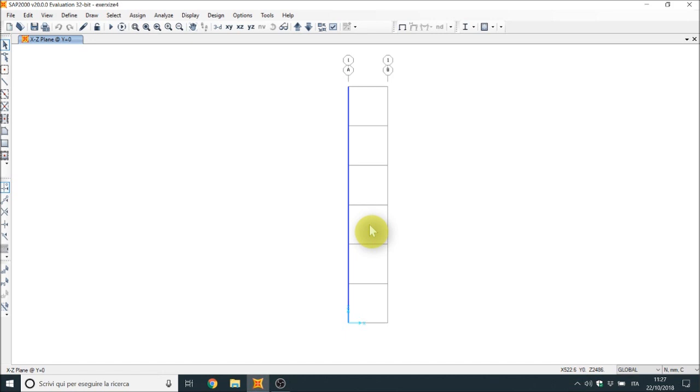Another method is always this global frame, perform first order analysis, this time using the same equation, but you have to calculate the buckling length that is greater than the geometrical length. So the length this time will be something that is greater than the geometrical length.